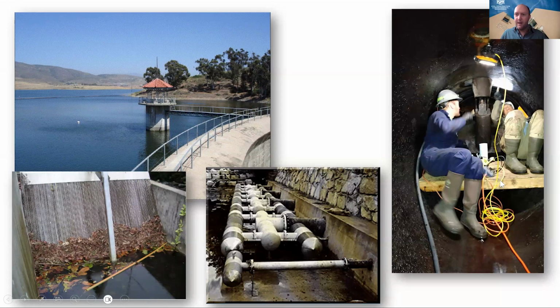And then the valves in the intake structures, like in this pillar, could look something like this. This is a big butterfly valve, I think 6 feet in diameter, that I was actually working on to repair cavitation, but I thought it was interesting. It's just a giant valve that was also very deep down in the middle of a reservoir.